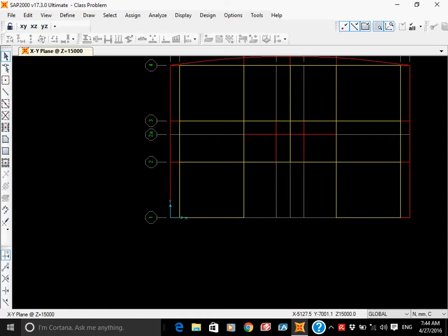For example, if there are a high number of stories, under the column the value of dead load and live load would be heavier. So the result would be a bigger footing size, because you know area of footing is equal to total load, dead plus live, divided by the bearing capacity. And if they start overlapping with each other, then we may combine them. But if still the bearing pressure is not satisfied, you need a bigger size, so then you can again go for the mat foundation.